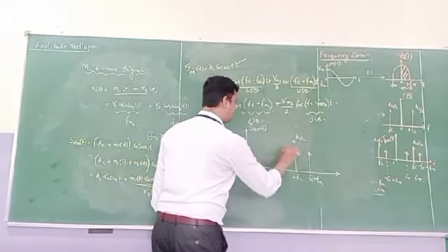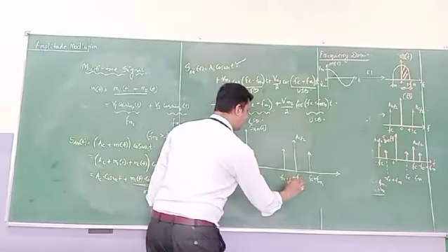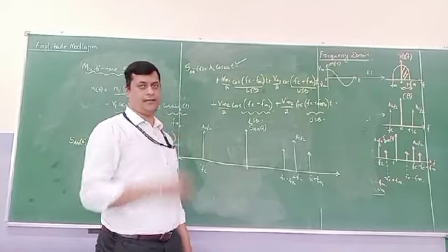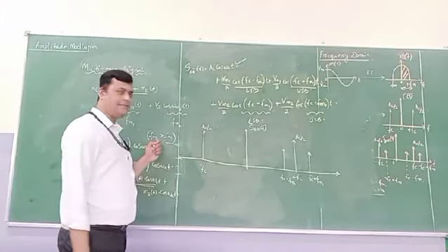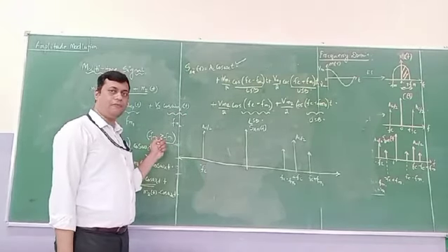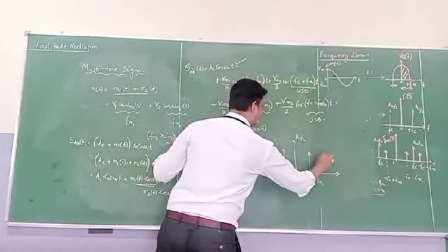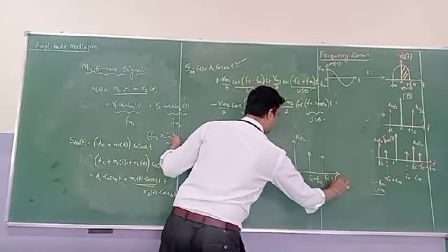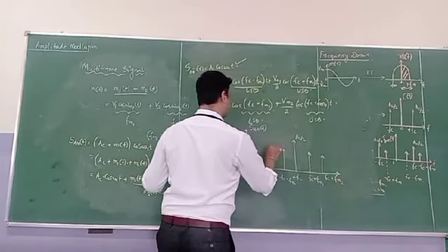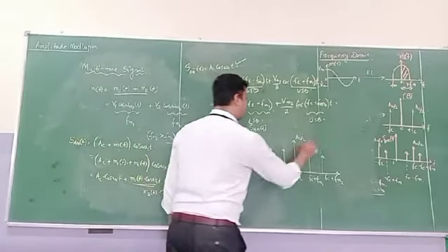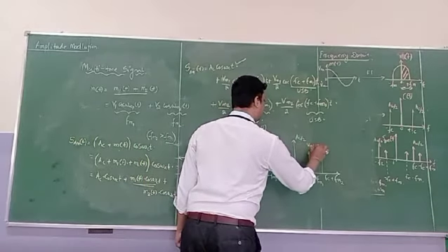Similarly, the lower side element is FC minus FM1. Then next, for the higher frequency component of the second modulating signal, since FM2 is greater than FM1, it will lie further out because it is greater. So it is FC plus FM2. Similarly, here I will represent FC minus FM2. These are the spectral components whose amplitude is Vm1 by 2.